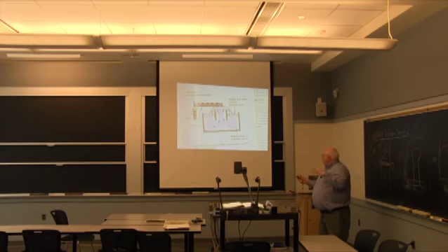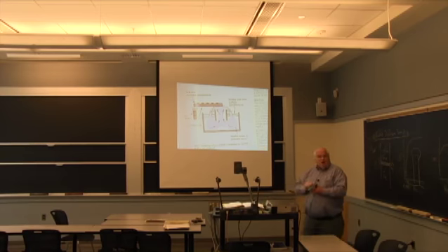But this shows everything flat, but anyway, you end up scouring off the oxides and the contaminants and making your wave soldering. We call it wave soldering. And your solder becomes the heat source to heat up the copper wires and everything else.